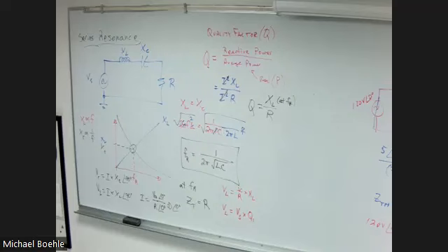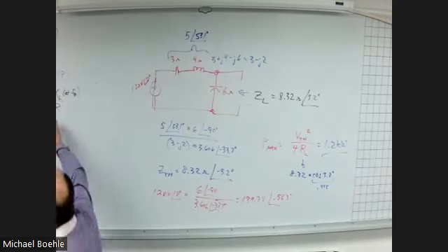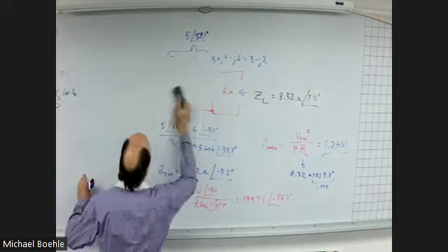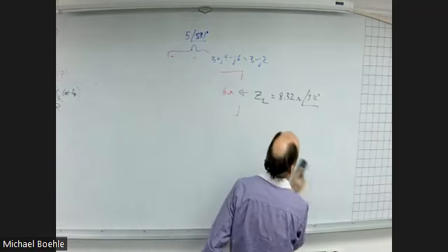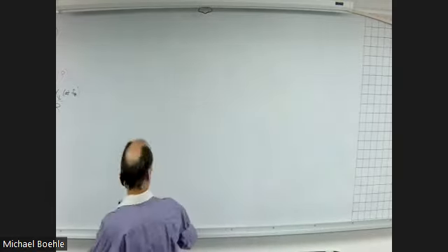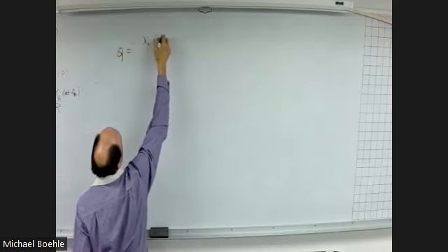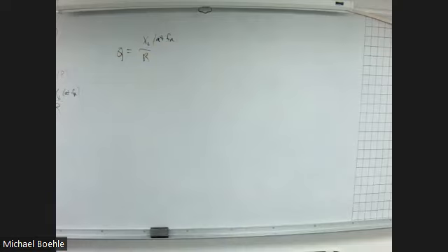Now, there are a number of other things we can do here with these formulas, all right? So we're going to be playing with lots of formulas here. Let's explore this a little bit more. The Q factor, I'm sorry, the quality factor. As I said, quality factor is equal to the inductive reactance at the resonant frequency divided by R. Well, let's go ahead and plug in.